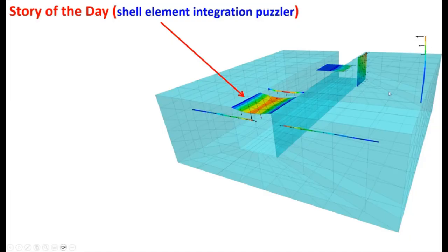Okay, I'm the guy who did all this stuff. I implemented all these structural elements in FLAC3D, and this is actually using finite element technology, and it's coupled with FLAC3D. So for example, the edge of this shell, you can see it's deforming. That's the deformation contours, vertical deformation. It's loaded by a pressure. You can see it's not deforming on the edges because those things are rigid zones. We call these things zones in FLAC3D. And so these things are coupled. And so this is a finite element thing.